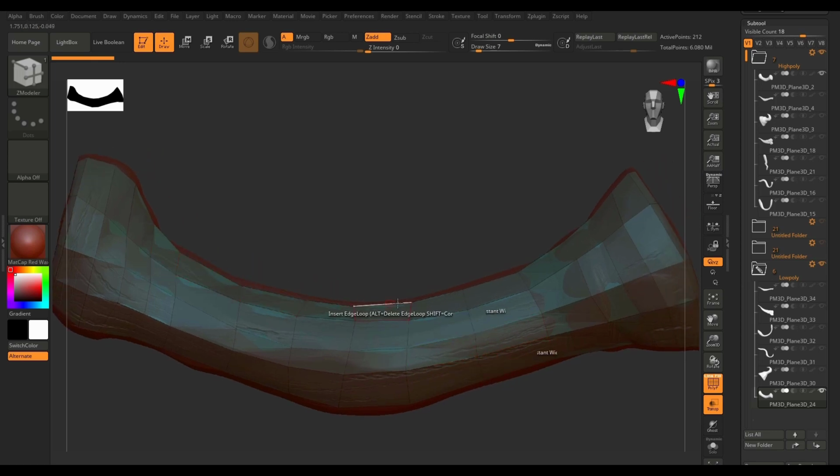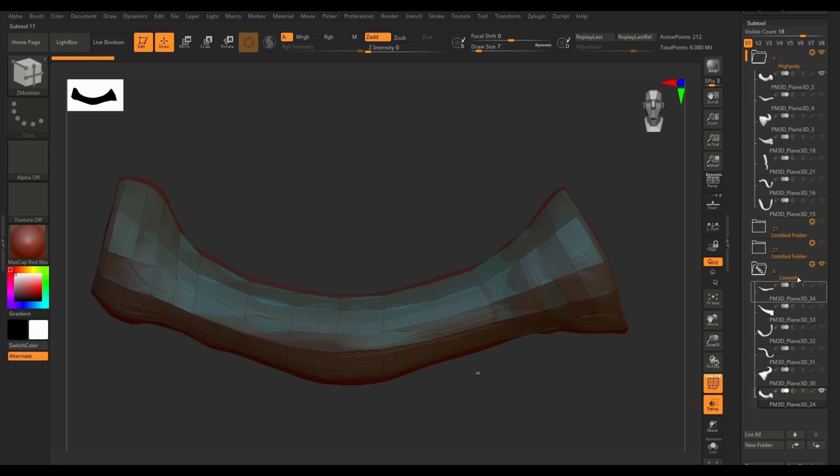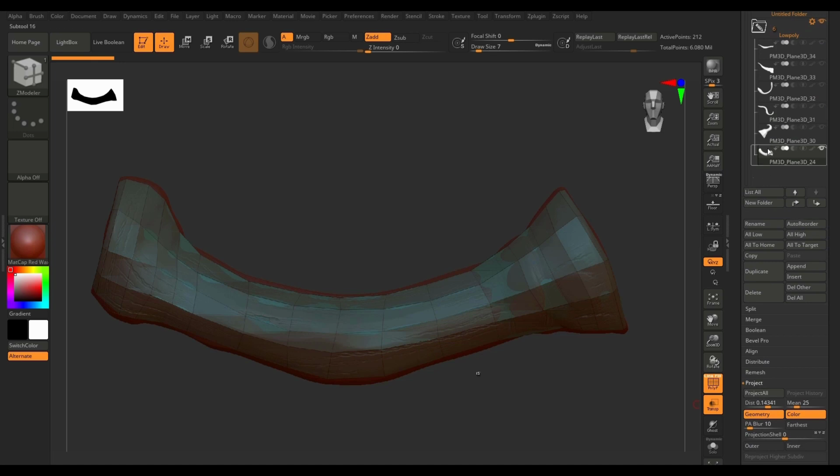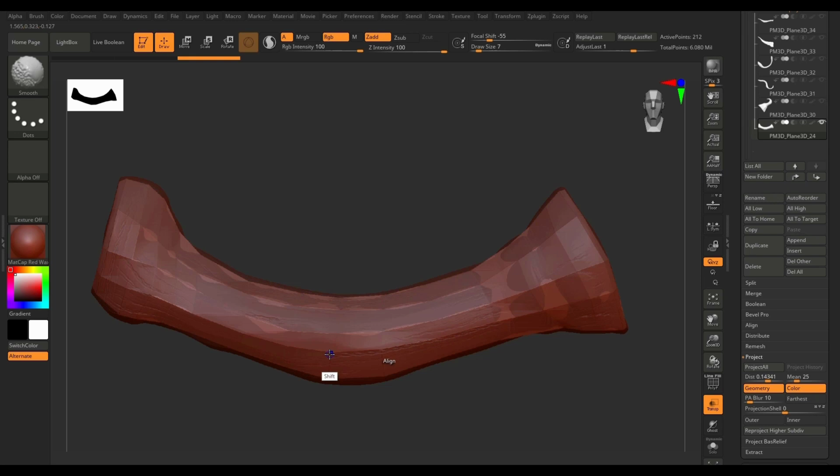As you can see, the low poly mesh is sitting inside the high poly, and that's not a problem exactly. That only makes the low poly handle a little bit smaller. So to solve that, select the low poly handle and hit Ctrl D to add a level of subdivision.